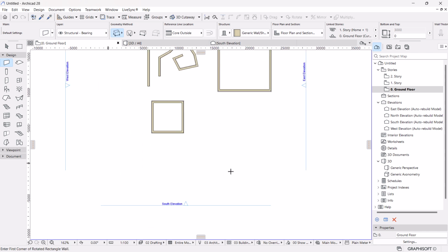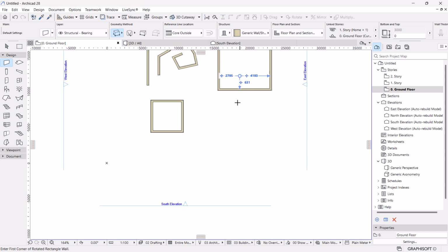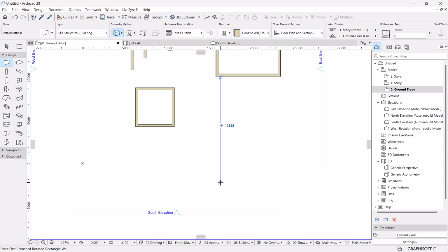Basically, it's more like just this box, but this one is different because you have to specify the angle before you can complete your box. For example, I'll enter the first point, then enter the rotation vector of this rectangle. In this case, I'm just going to follow this guideline of 45 degrees, then I can click, then drag accordingly, like so, to draw.